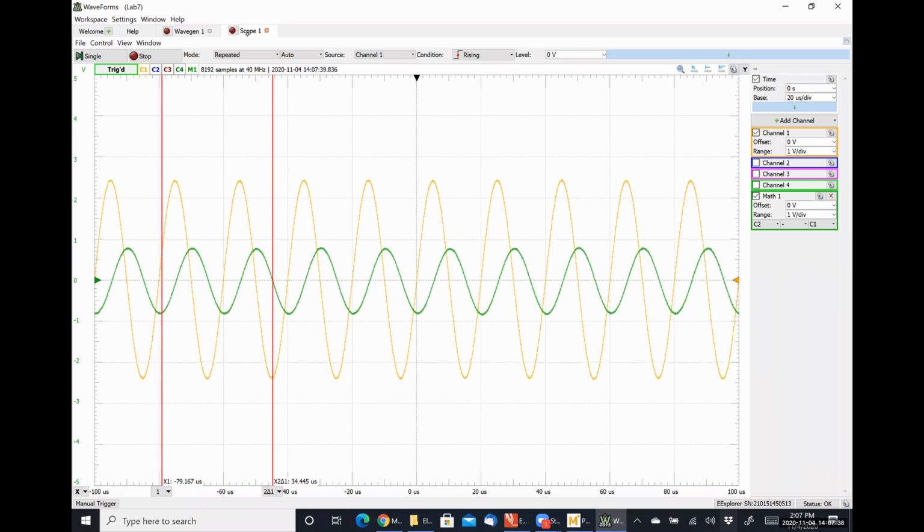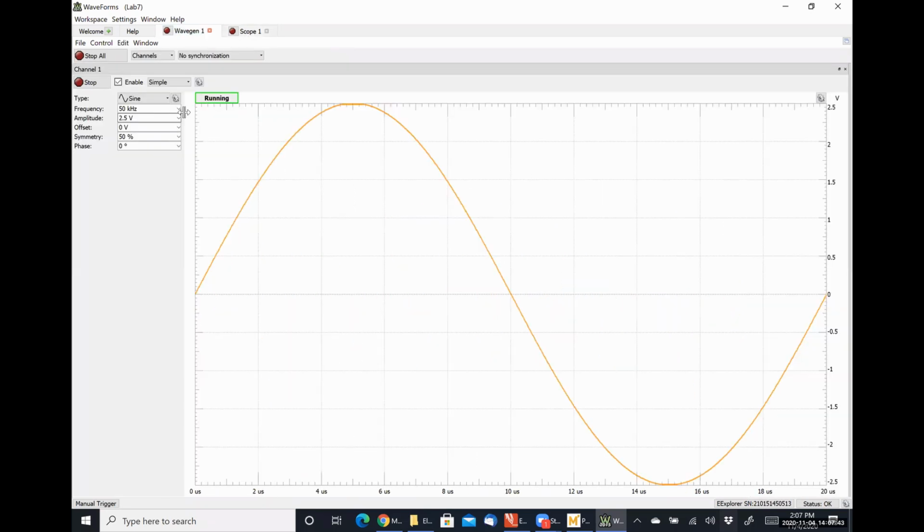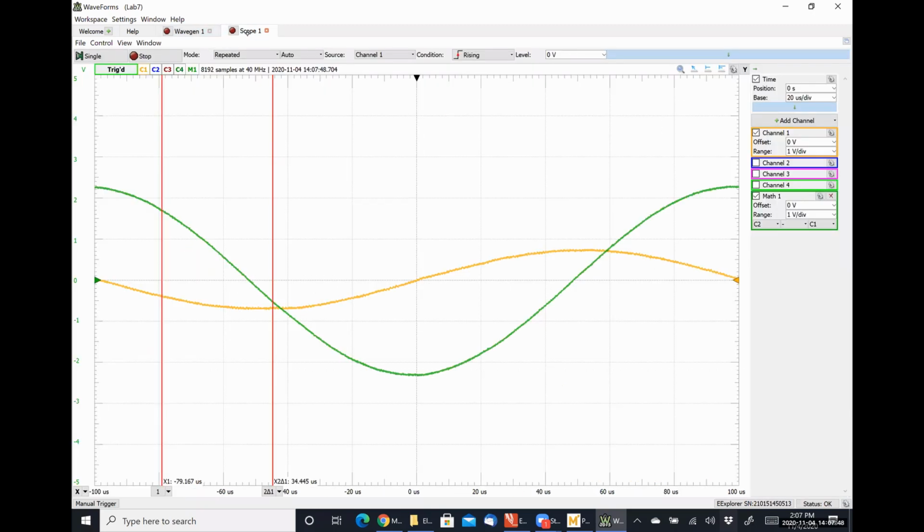If we change the frequency to 5 kilohertz, we still see that our voltage leads our current, because that will literally never change. But obviously, lowering the frequency causes the impedance of the inductor to decrease, which means we should see the voltage drop go down and the current go up. Does that make sense to everybody?